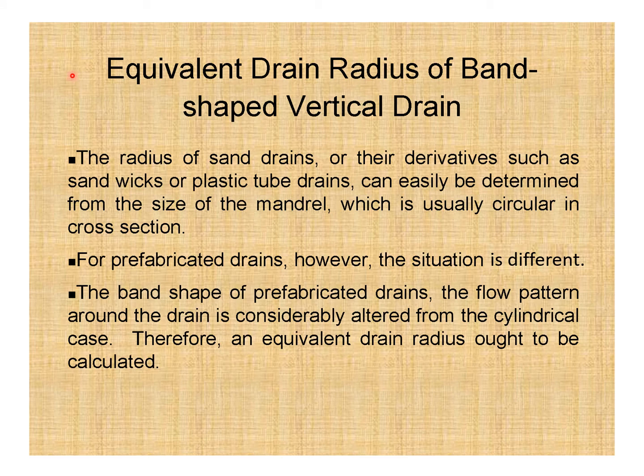Equivalent drain radius of band-shaped vertical drain. The radius of sand drains or their derivatives such as sand wicks or plastic tube drains can easily be determined from the size of the mandrel, which is usually circular in cross section.